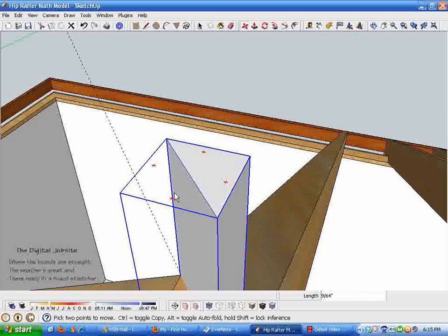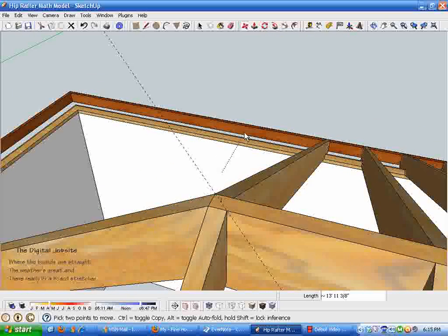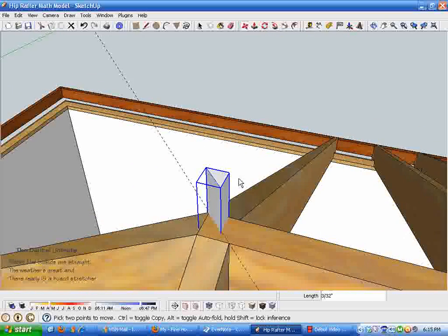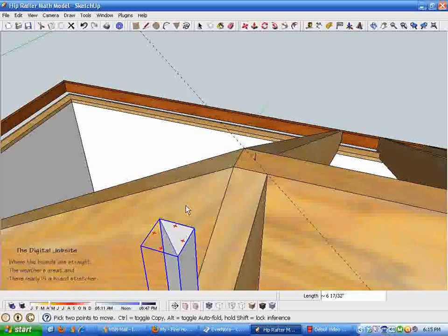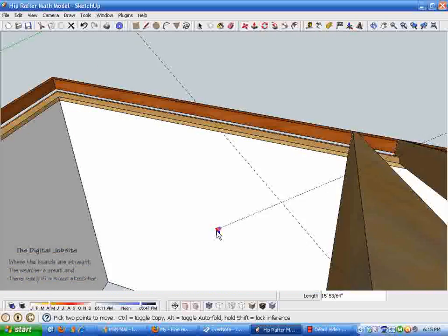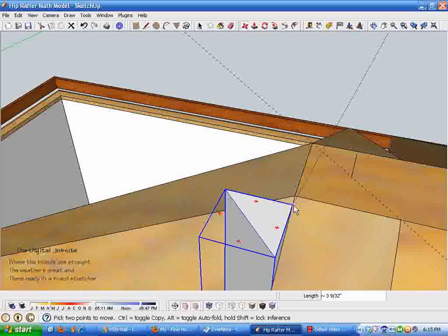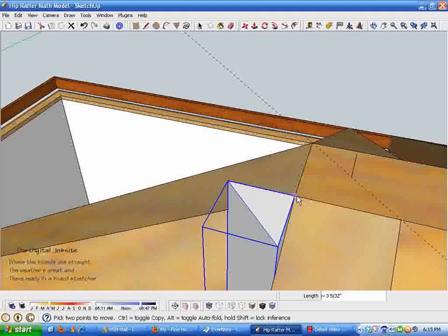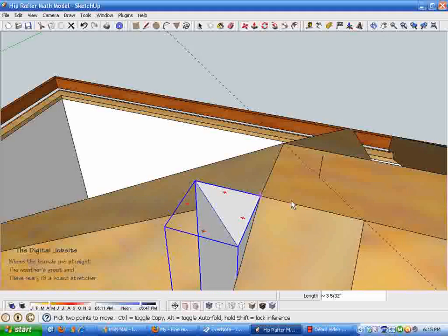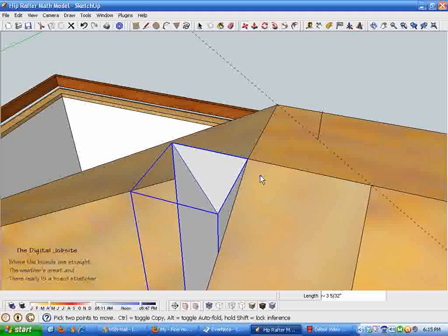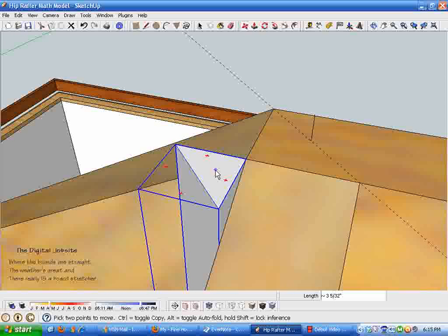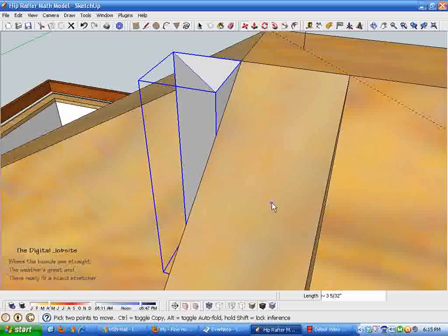I don't want to just grab it willy-nilly like you would with your hand picking it up. I'm grabbing it by this particular corner because I want to line those two corners up there. If I select the geometry at the point that I want to connect, then that's what SketchUp will target it to. So it's a lot easier to position this little wedge precisely at that corner.